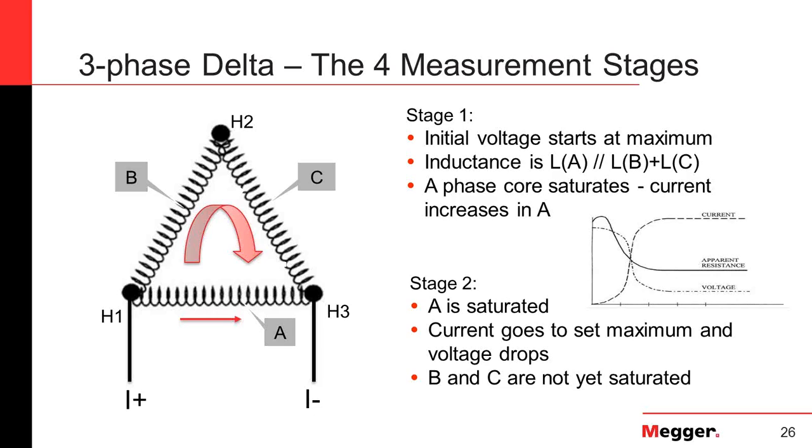also carries current, in this case 10 amps, and shares that 10 amps with the H1, H3. So A phase has only 2/3 of the current. B and C phase have 1/3 of the current flowing through them. That is not so bad, but the voltage across H1, H3 is 50 volts, yet the voltage across H1, H2 is half of 50, and the other half goes H2 to H3.